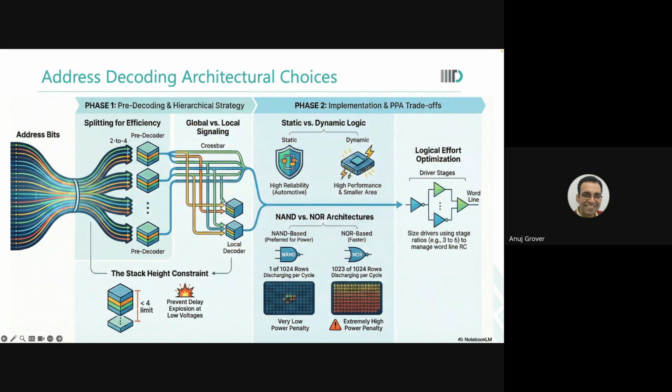See, what we just talked about was that if you have implemented mux, then bit interleaving is here. It is independent. Whether you're talking about a page or a bank or something, you've done bit interleaving. Which address bits you use for decoding the mux will decide which words will sit next to each other. That is all I'm saying.